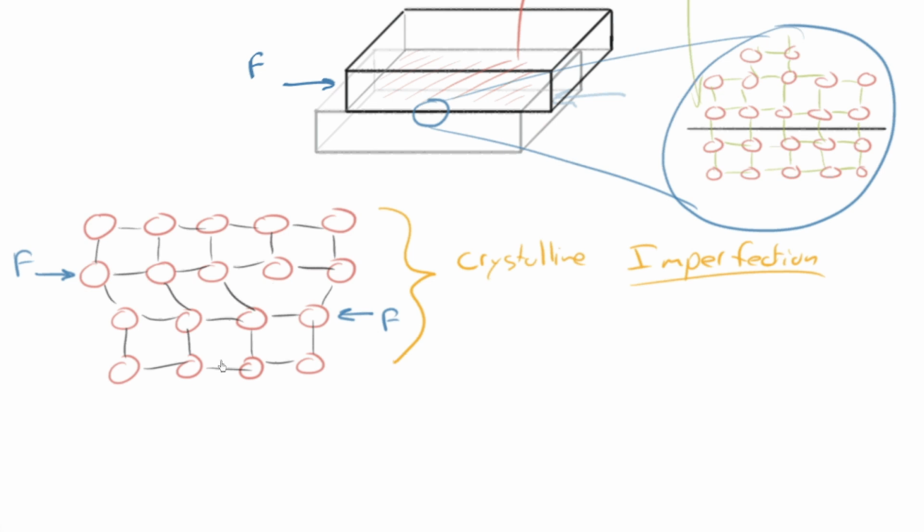So there's what we started with. A bond breaks, another bond breaks and reforms. And it's that step-by-step movement of bonds that is the mechanism for plastic deformation. So it's a step-by-step breaking and reforming of bonds. That is the correct mechanism for plastic deformation in a metal.